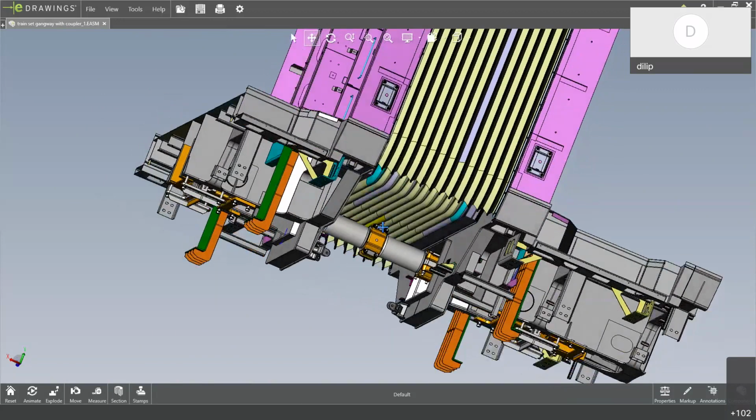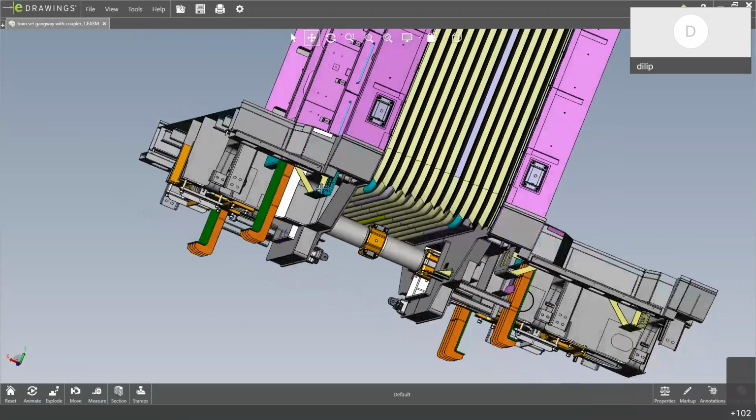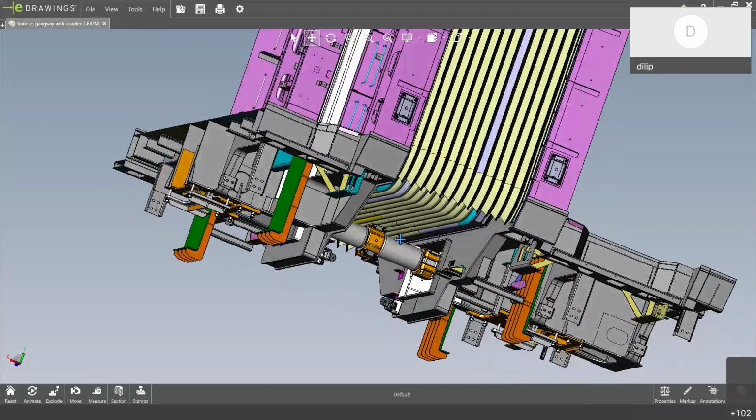To facilitate this, actually, if you see in the Train 18, the coupler height is 940 mm, whereas in our regular coaches, the coupler height is 1105 mm. And this is a semi-permanent coupler. So the coupler height has been lowered so that we can fix this flexible gangway.